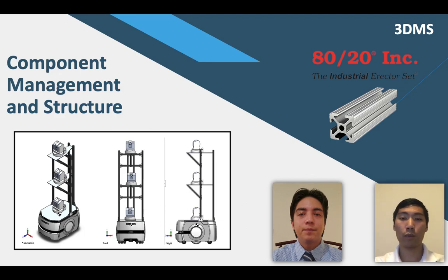The structure was designed with two main sub-assemblies, the platforms and the base. The platforms can be adjusted to the required height and can support devices including cameras. The 45-degree support bar was added to reinforce the platform while reducing the nodal vibrations within the structure. The base holds up the platforms and connects rigidly to the Omron LD90. The total weight of the attachment is 18 kilograms, which is within the 90 kilogram maximum. The entire robot has a low center of mass, and analysis confirms it would not tip while moving or stopping.